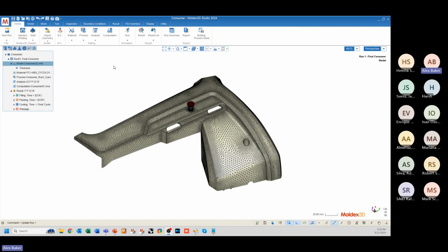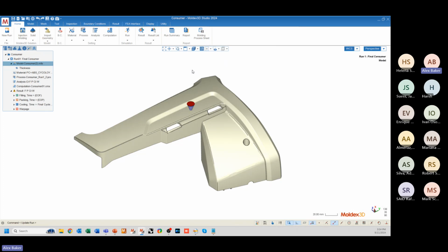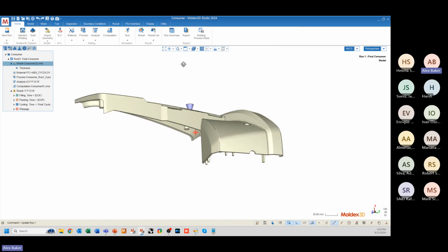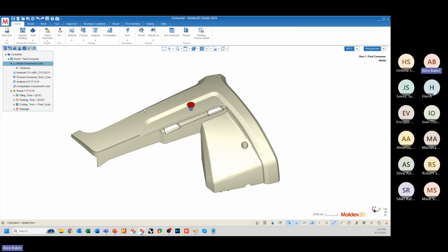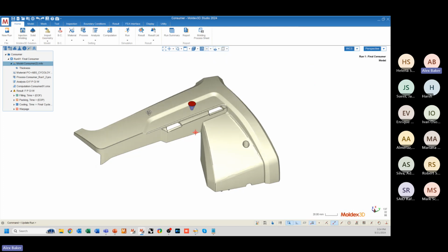All right, and so I'm going to go up to the top middle of my modeling window. And the centermost button, the one that looks like an orthographic cube, I'm going to click the drop down and go to the third button, which is show feature lines with shaded faces. That's just going to turn off my mesh lines. Once again, it's just going to allow me to see the color contour, the blended display, a little bit easier.